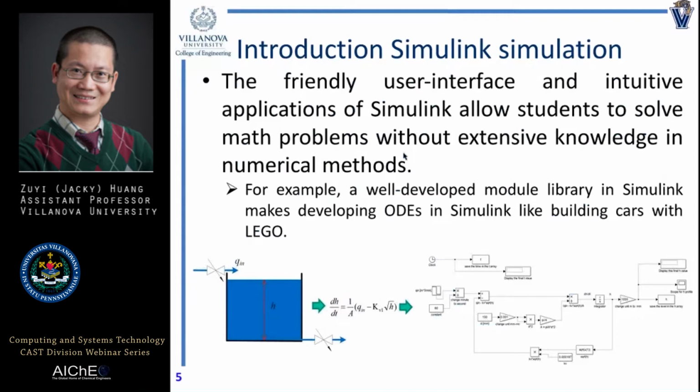And so one tool is MATLAB Simulink. So for example, for this water tank, we use this ODE equation to describe the liquid level in the tank, and then we could develop the model for this equation in Simulink just by linking those modules provided by Simulink together. And this is just like a kid playing Lego.